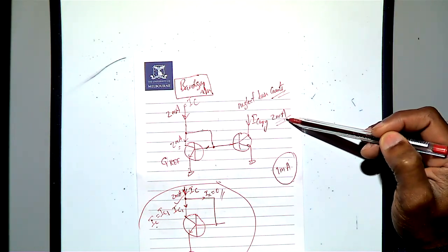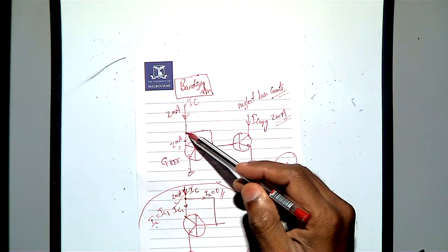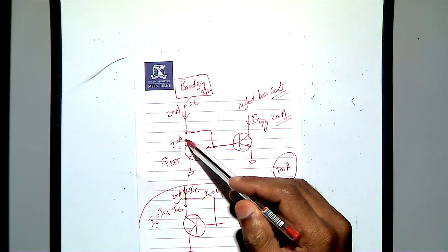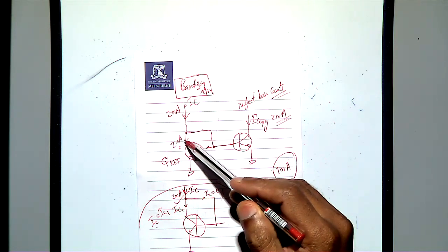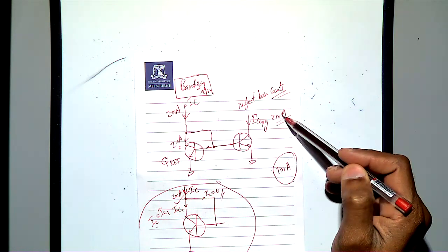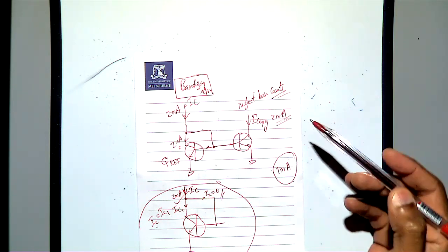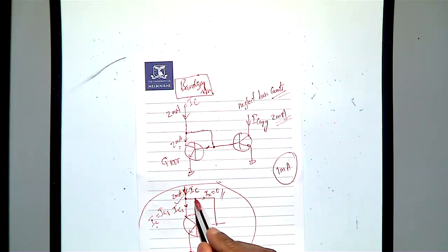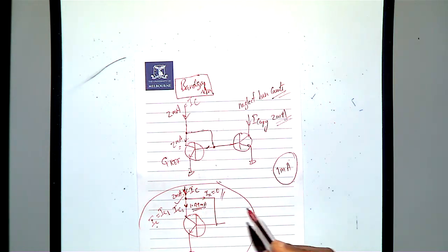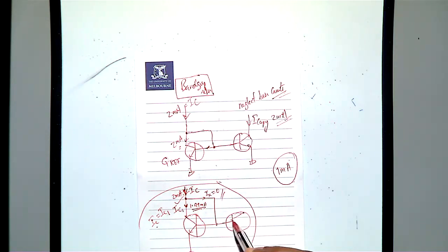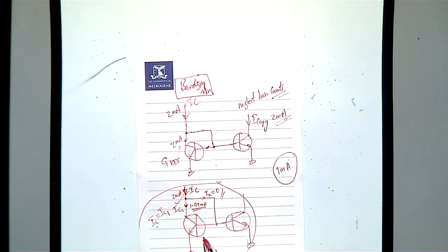If that is not the case, what will happen is a little bit goes this way, and then this current will be less than 2 milliamps, and this is actually duplicated here. You know what I meant? See, here this is 2 milliamps. Then IC1 is going to be 1.99 milliamps. And then here when you connect another identical transistor, then this 1.99 milliamps, so your IC